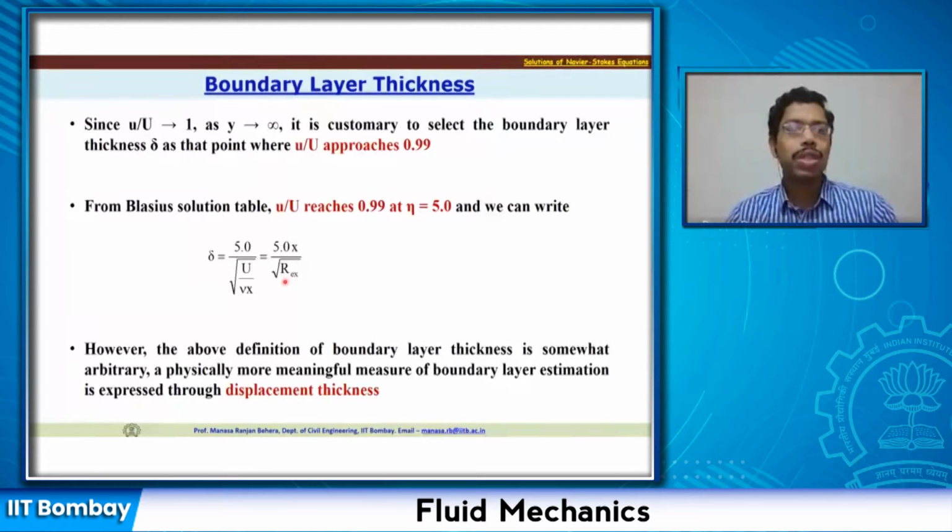So that's why there are different terms which are used to identify this boundary layer thickness. The definition we have given above for the boundary layer thickness is somewhat arbitrary, and a physically more meaningful measure that is used for estimation is called displacement thickness.